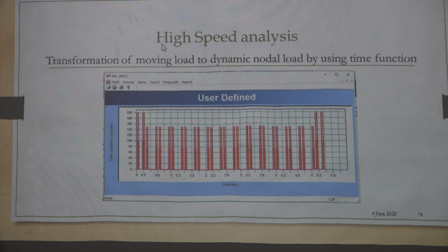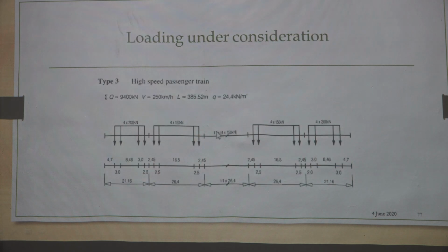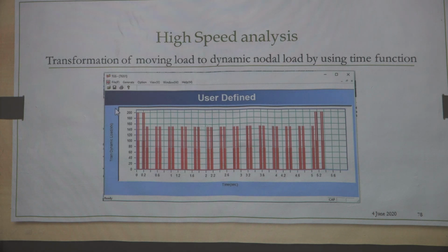So, the important task now is to consider this loading protocol on the actual bridge. MIDAS has a provision to transform the moving load to a dynamic load. We are supposed to convert this loading protocol into a time history, and only then can we give it as input to the software. So, MIDAS has that provision; this is the input for the type 3 case we have considered, and MIDAS will end up with this particular time history, and we can directly supply this time history to the software to do the analysis. This is the last slide I wanted to discuss with you.